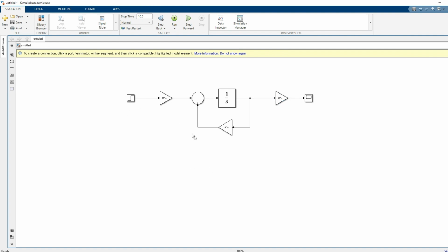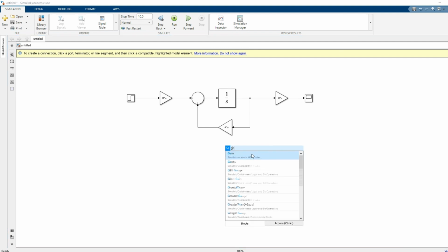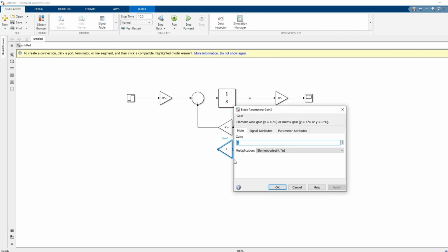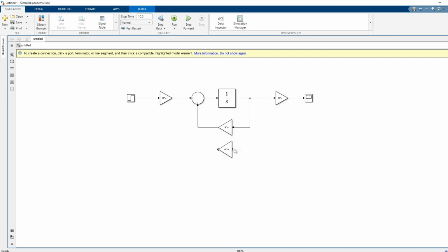Now, if I want to apply a feedback to this system, I will need another gain block, Control R. So, it gets rotated. So, I will take K here, in other words I will take minus K here, because my control law is u equal to minus Kx plus Nr. So, minus K matrix multiplication, and so you can put it here.